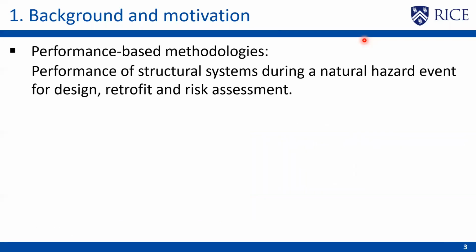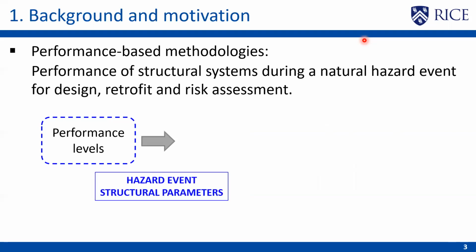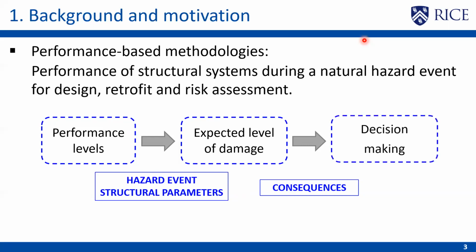To assess these, performance-based methodologies have been used to assess the performance of structural systems during a natural hazard event, for design, retrofit, and risk assessment of structures. So it starts by defining some performance levels. These are qualitative measures of the performance of the structure, such as operational or life safety, that are coupled with hazard events and structural parameters to compute the expected levels of damage of the system. The consequences that these damages lead to will give us some decisions.